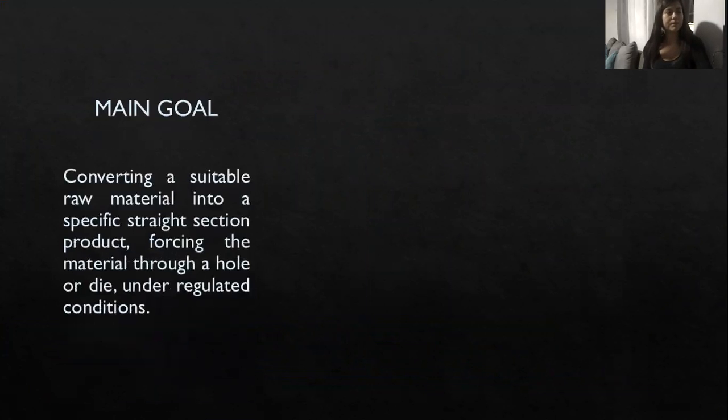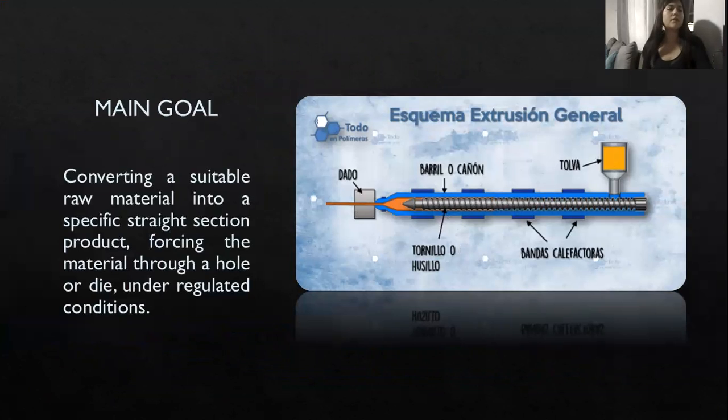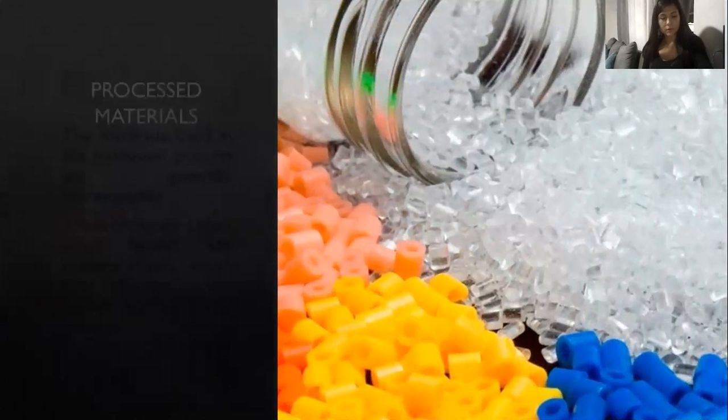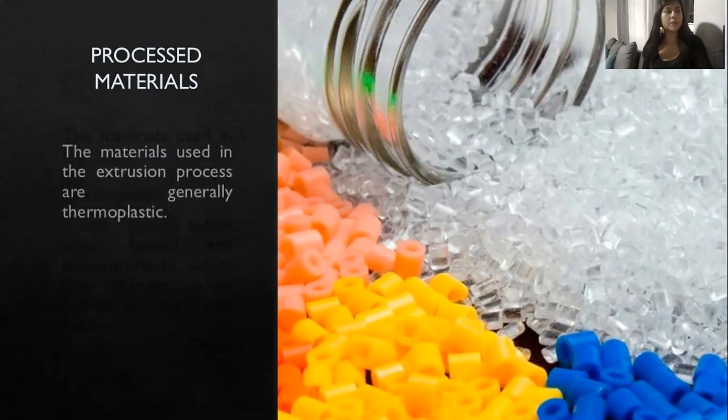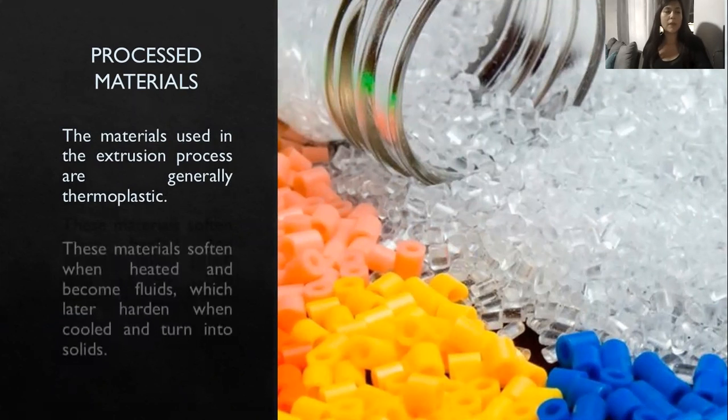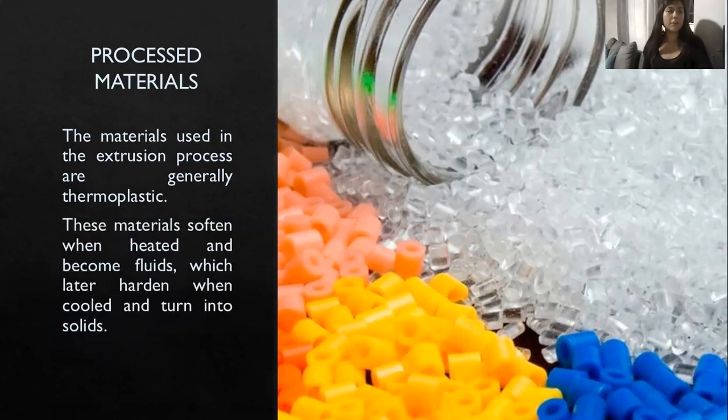The main goal: converting a suitable raw material into a specific cross-section product, forcing the material through a hole or die under regular conditions. For the process materials, the materials used in the extrusion process are generally thermoplastic. These materials soften when heated and become fluids, which later harden when cooled and turn into solids.